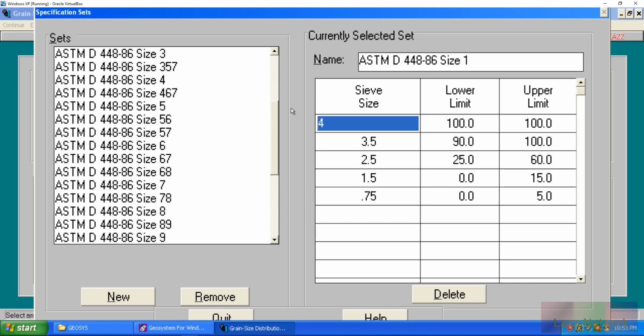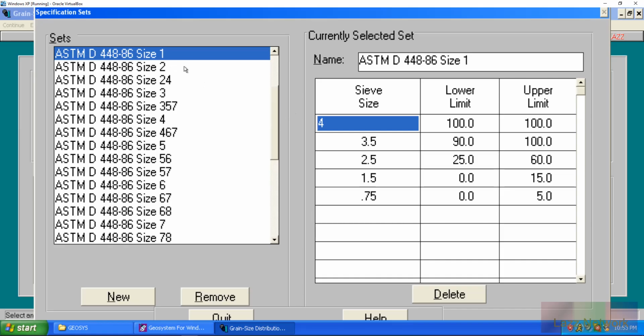So these number designations, you would probably think, and for the longest time I always thought, okay, so if your number size is small, that means your aggregate's small. But as you can see, if we have number one aggregate, as people would say, or number one stone is what it's typically called in the industry. So everything here, they call it stone. So somebody's like, hey, I need a number 57 stone for this.